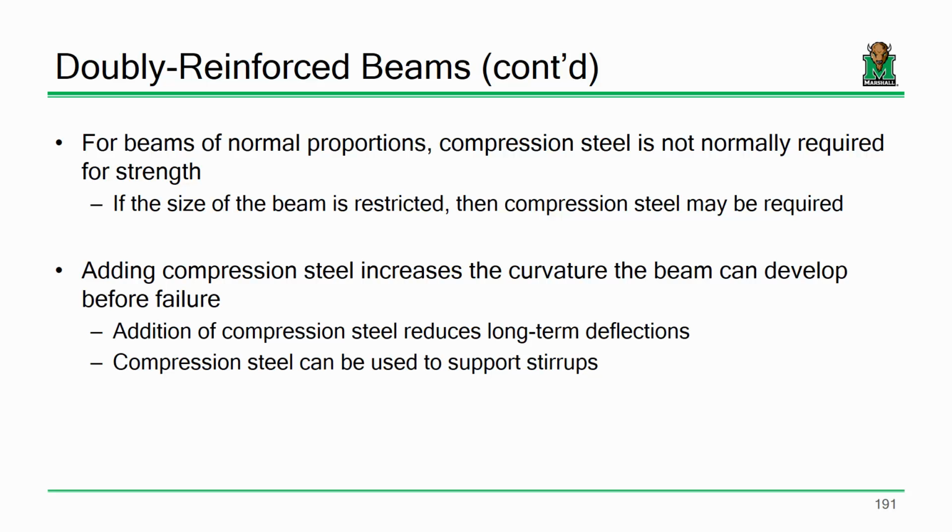There's an opposite effect that actually happens in steel. In steel, under a constant length, the force can dissipate. You can get reduced force. That happens in pre-stressing strands in beams, and we call that relaxation. There's also another very familiar example of relaxation. How many of you have ever played a guitar?